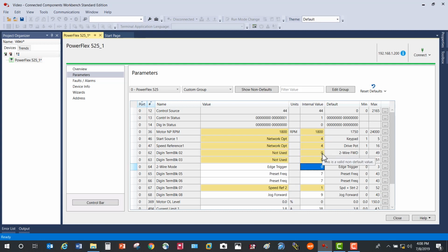The reason for doing that is if you have a stray wire that would land on those blocks, they will override the existing configuration and likely give you added time in troubleshooting. If you don't program them, they will not activate then.